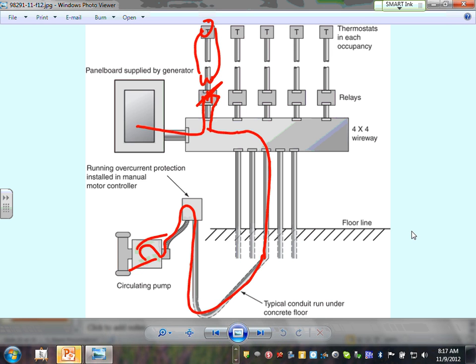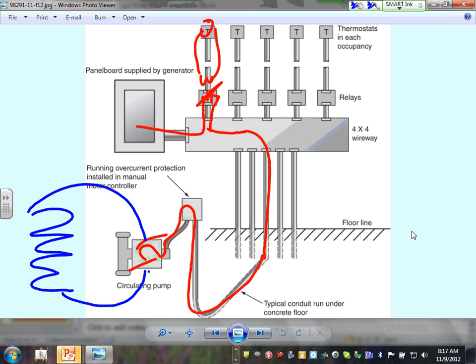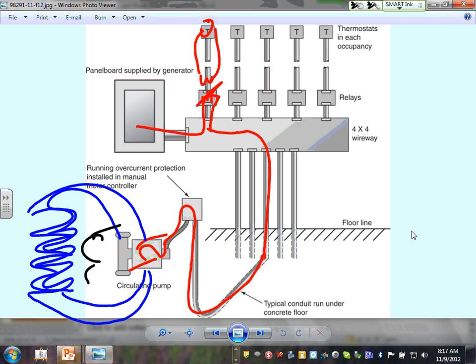When the pump is running, it starts taking. Now this is water. What you're looking at is water. So it starts pushing water through these pipes. Right, hot water. Then they have a fan. This is a fan, and the fan blows air through these coils. They're water coils. Here's hot water and we're throwing the air through these coils.